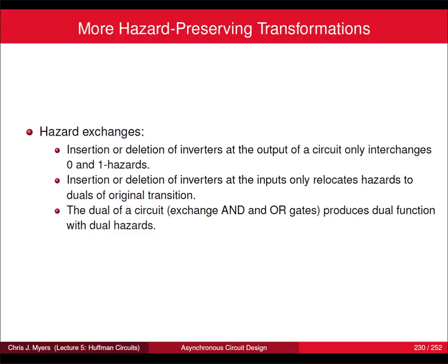Right. So first of all, logic hazard, not data hazard. Data hazard is a computer architecture term. But yes, every function will have hazards, but the hazards that you see are not necessarily hazards that you care about because they're not transitions in your burst mode machine. So what you do when you do hazard-free logic synthesis is you eliminate the hazards that can happen due to transitions you actually could see in your machine.